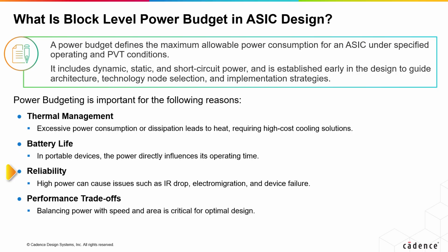Reliability is another primary concern. High power can cause voltage drops across the chip, accelerate wear-out mechanisms like electromigration, and ultimately lead to device failures. So keeping power within budget is essential for ensuring the chip's longevity and robustness.